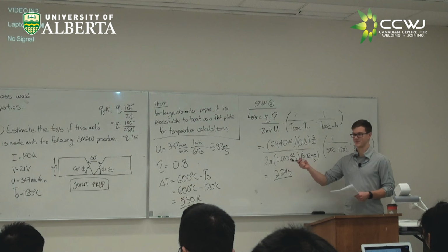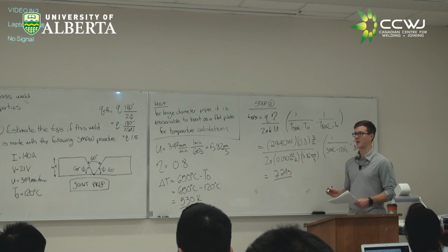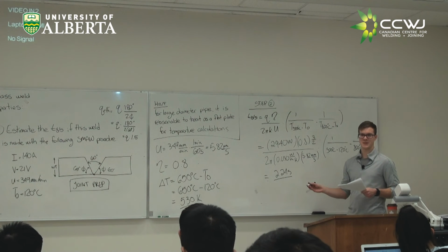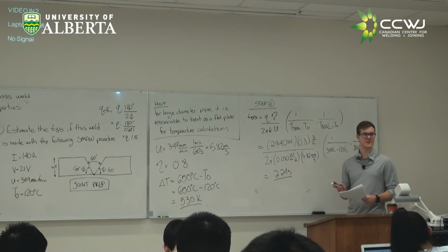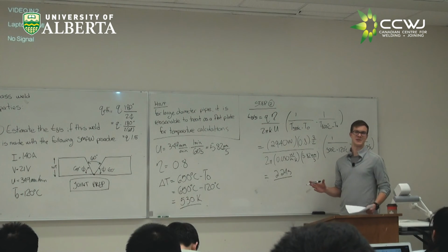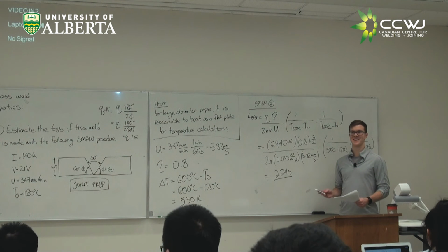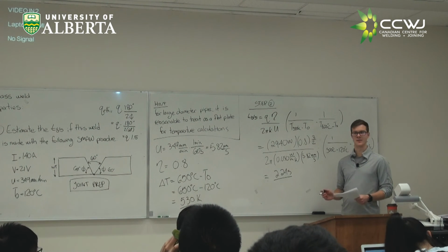Typically, we're probably adding preheat to avoid formation of undesirable microstructures. Now, in this case, we weren't given the composition. We don't know exactly what the steel is. We don't know really what that critical T85 is going to be to form martensite, but 2.2 seconds seems reasonable. It's not a microsecond. It's not an hour. Seems like something you could encounter in welding.